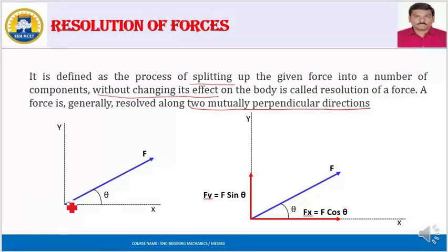Imagine the force is acting on this body. The resolution of forces means we can split the force into two components in two mutually perpendicular directions, the x-axis and the y-axis. If I resolve the force along the x-axis, I get Fx equals F cos theta. If I resolve it along the y-axis, Fy equals F sin theta. So this is the final formula.